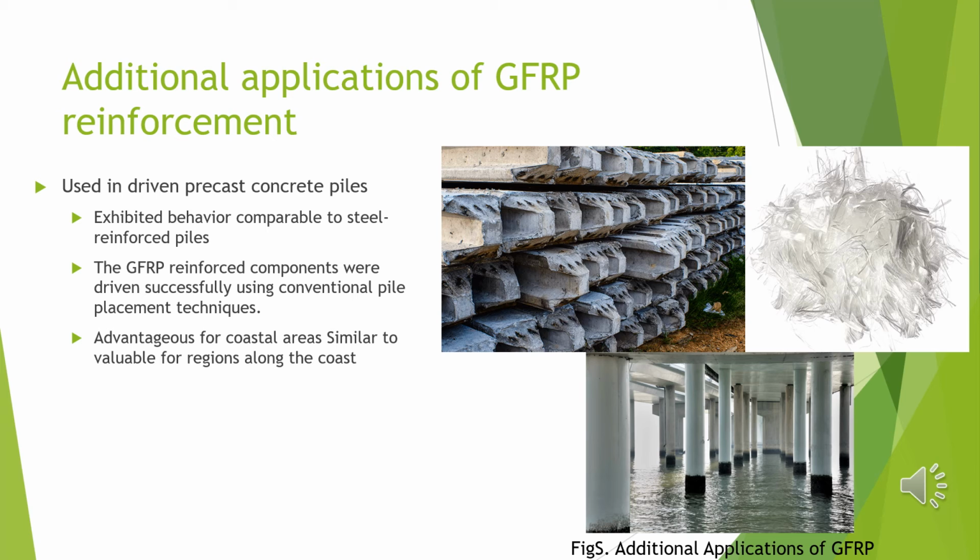The study by Bancroft in 2020 noted that laboratory tests of GFRP reinforced piles showed behavior similar to traditional steel reinforced members, and traditional pile installation methods were successfully used for driving the GFRP reinforced members.